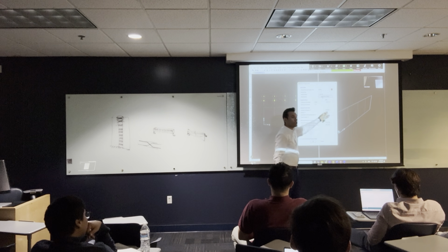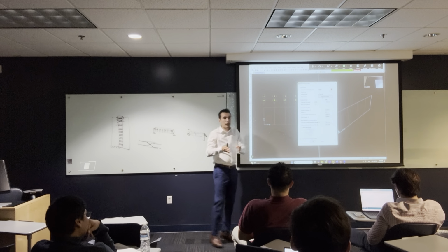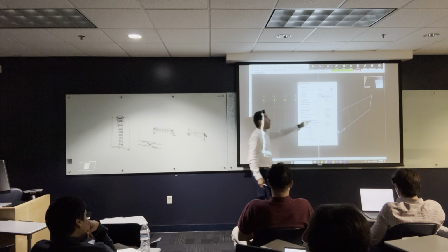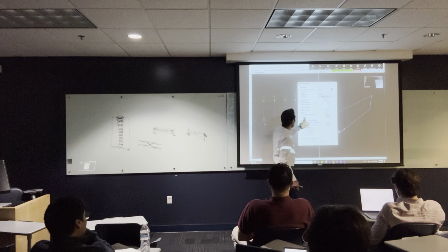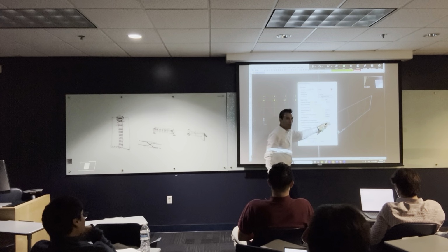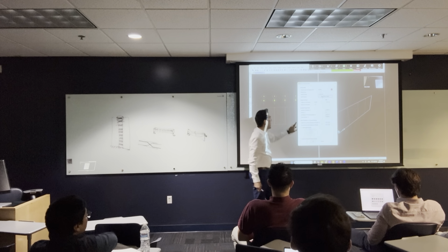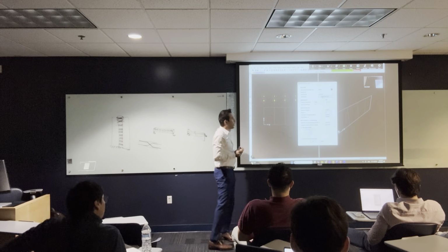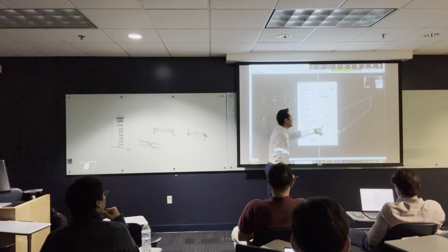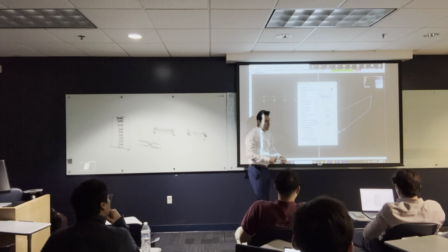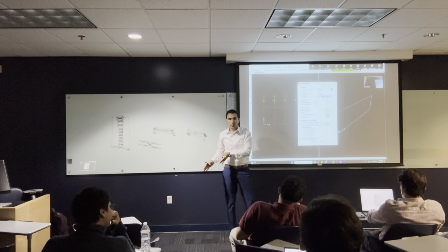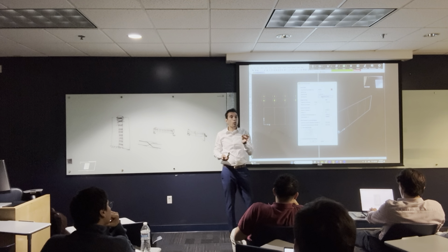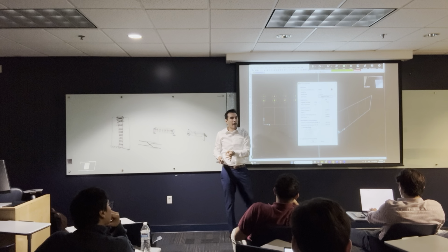And the Poisson ratio, which is the relationship between the lateral strain over the longitudinal strain of the concrete, is always 0.2. And here is something called the coefficient of thermal expansion for the concrete, and the shear modulus, which we'll rarely use. And here, there are some parameters for design, because when you do design, you need to know the compressive strength of the concrete. We're not going to do design in this course, but you have to know what the FCU of the concrete is, and how we can know that.